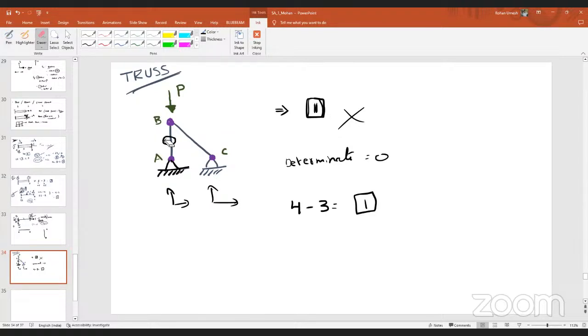Yes, sir. Now, I'm telling you that these are truss cases. If it is a truss member, which type of forces will the element carry? They will carry only the axial force, isn't it? So member AB will transfer which type of force to the support? As it is resisting only the axial force, it will transfer only axial force to the support A, isn't it?